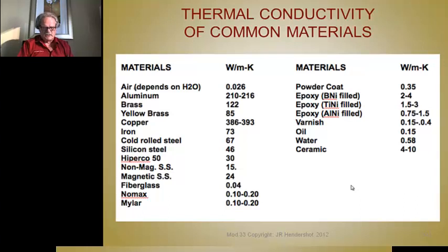Anytime you study the thermal conditions of an electric machine, it's good to have in mind what the thermal conductivity constants are for all the common materials, in particular the ones that are used in a motor. So we have a list here that we've compiled, and these are in watts per meter Kelvin, and this includes all of the materials used in a motor. I think it includes them all. Hope we didn't miss one. Plus it includes some other materials for reference that aren't used in a motor. I think there's a couple there. So you see there's a wide variation.